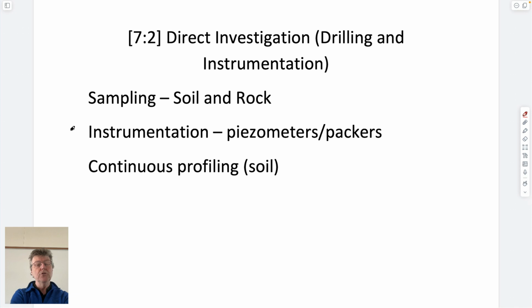If you're drilling, you need to use different methods if you're going through soil than if you're going through rock. Soil would be augering or using maybe rotary drilling with a tricone bit, but not taking samples as you go down. And rock drilling would be using a tricone bit, which doesn't take samples but takes cuttings at the surface, or a rotary drilling with a diamond drill, which does take samples, which we talked about last time.